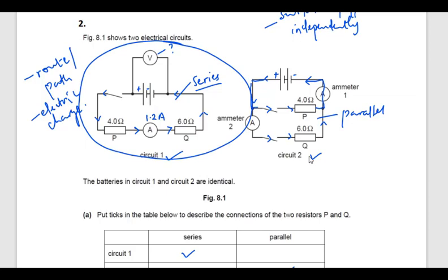Because it's a series circuit, we have to note the total voltage, but we don't know which is this. But there's one thing that we can do, because I know that I have the total current flowing in this circuit. I can find the combined resistance of these 2 resistors. Once I know the combined resistance of the 2 resistors, then I can use that to calculate the voltage.